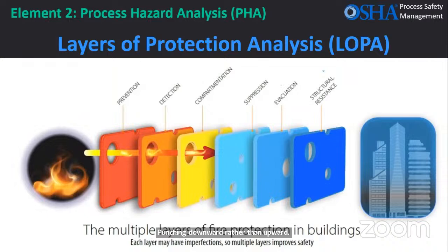Our last risk analysis technique is the layer of protection analysis, LOPA. LOPA is one of the very comprehensive risk analysis techniques. Depending on the existing layers of protection the designer has constructed for your process, plant or business, it analyzes each individual layer of protection. Is it functionally working well? Does it need some modification? Does it need some verification? Can it stand against the risk it is built for, or shall another layer of protection be constructed to control your hazard?